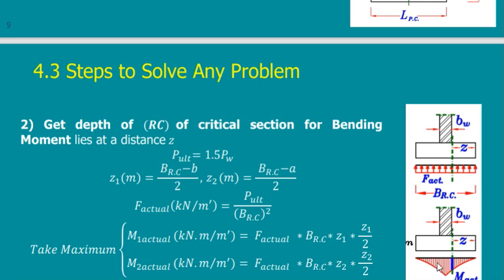But now we need to speak about cost a little bit. To reduce the cost of everything, I can calculate the bending moment as WL squared by 2. What is L? L is the length of the cantilever. Usually you may think that you would just take it from here to here. This is L. But actually I need the moment at the edge of the column.